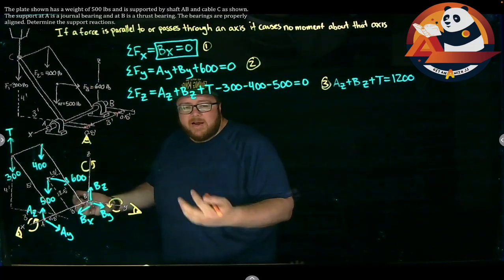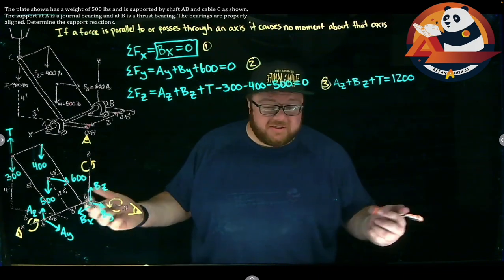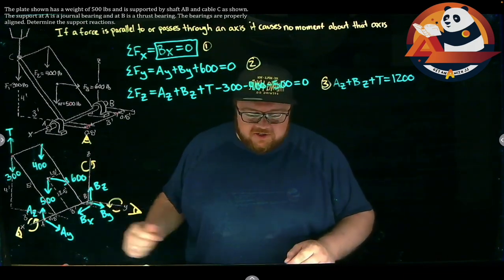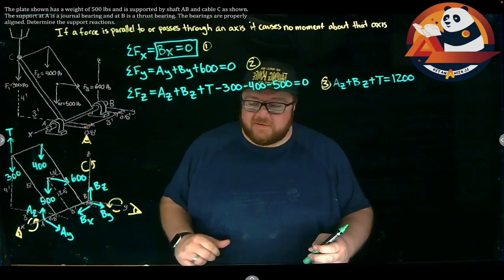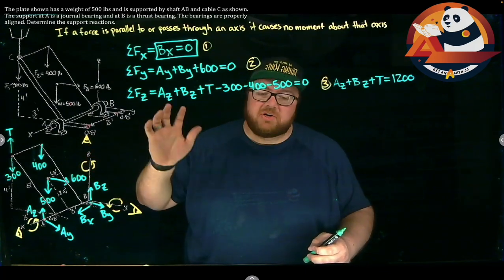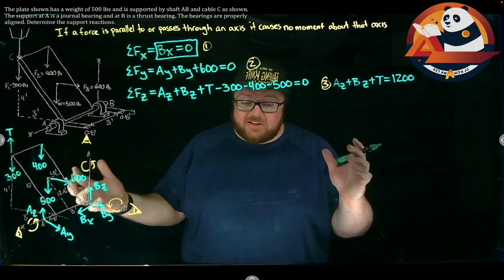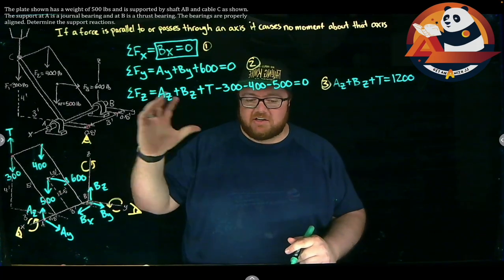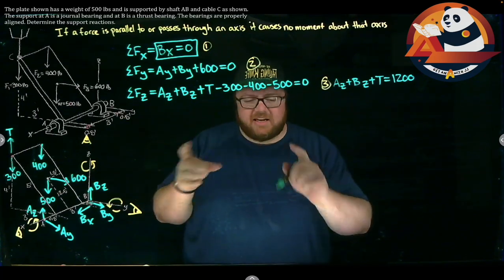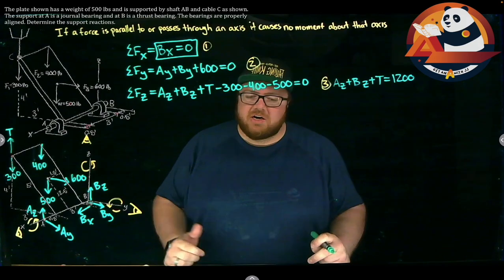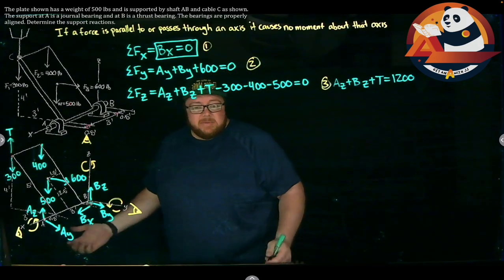We have to be able to wrap our head around that for this method to work. Otherwise, we're just guessing blindly on rotation directions, and it doesn't work well. So if this doesn't work for you, use the cross product. If this works, it's a little bit easier, just force times distance. There are less of the tedious calculations of the cross product. But let's come in and try to do this.